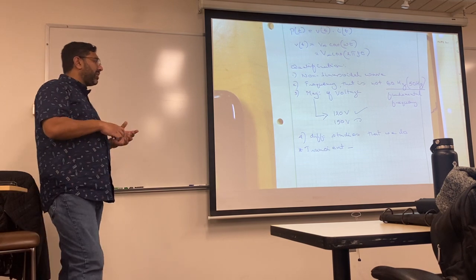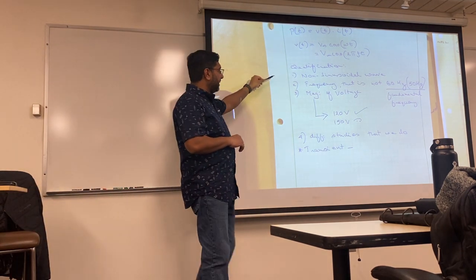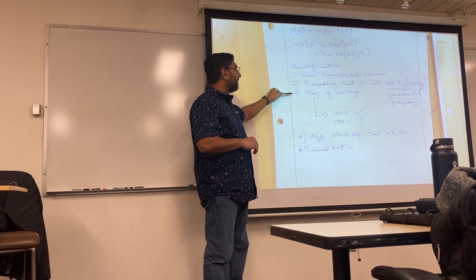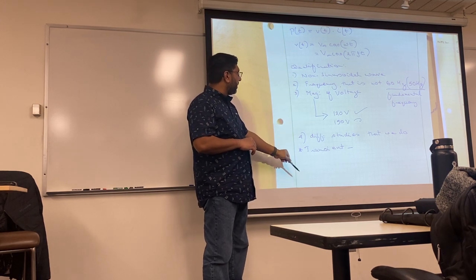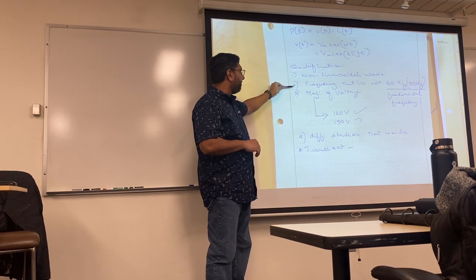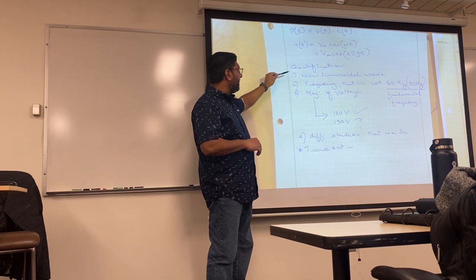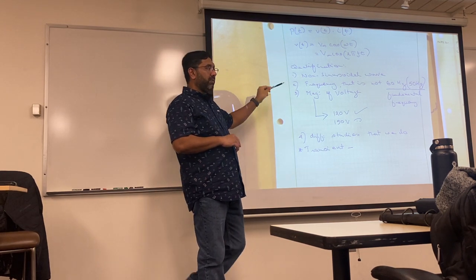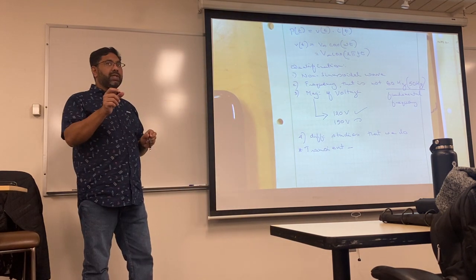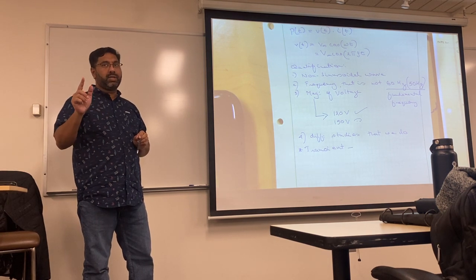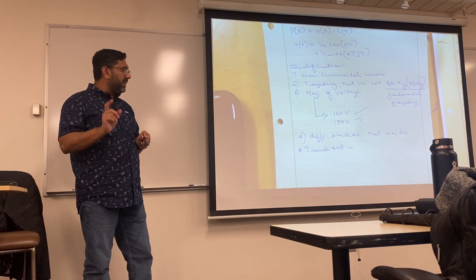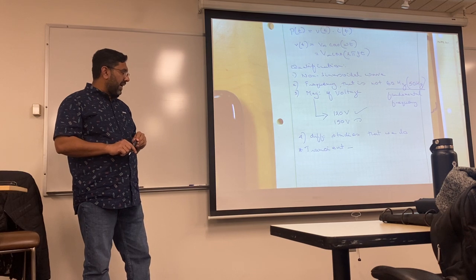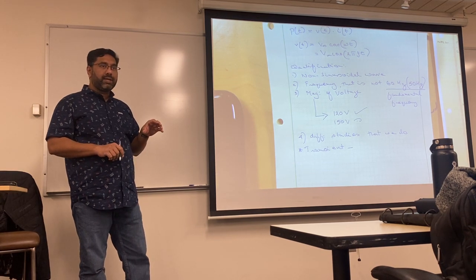And what I mean by quality of power are these three things. I need to make sure that I'm still giving you 120 volt at this point. I need to make sure that the frequency is 60 hertz, and I need to make sure that I'm sending you a sinusoidal wave. Chances are, for the first few cycles, we may not be able to do that. And there are ways and means to suppress that.